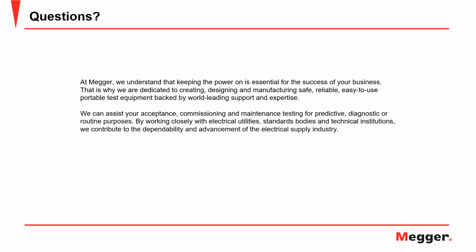So power factor testing, or capacitance value, is an indication of the condition of the insulation and how you operate and how you treat your transformer. That is going to be a big factor that would define the power factor values staying stable or increasing over a period of time.